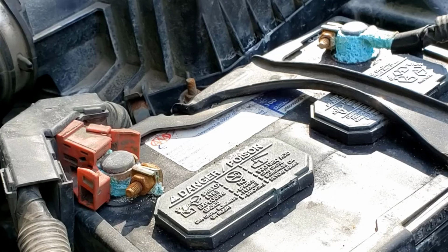I'm going to play you a video that demonstrates how to clean battery terminals. Before we remove the terminals from the battery, I'm going to show you how I hook up Keep Alive memory to provide a backfeed of battery voltage to the vehicle's electrical system so that we can maintain memory. Once that's done, we can remove the terminals from the battery.